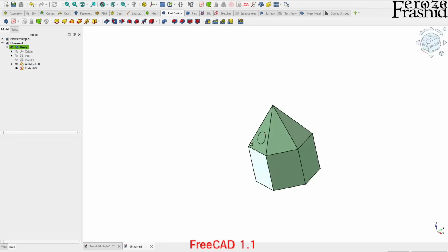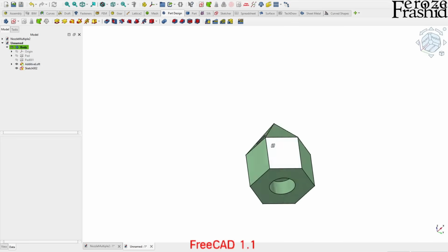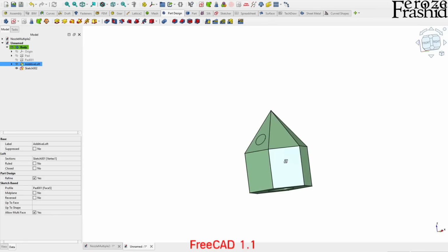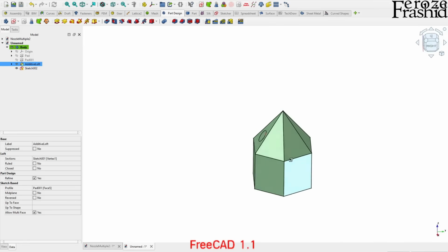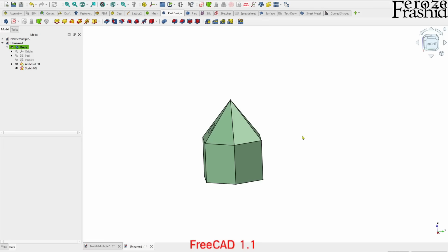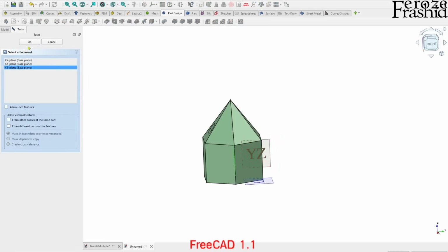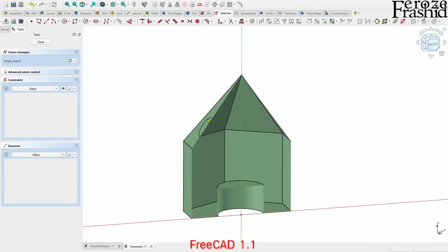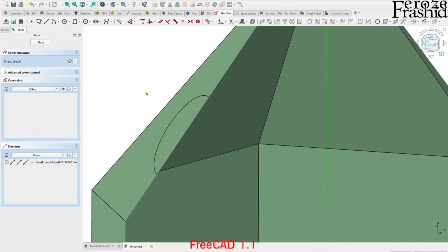Now what I'll have to do is make a pipe with this face and this face. So there will be a smooth transition between them. So we need a sketch to have it. So let's draw another sketch that will be the pipe path, which should be on the YZ direction. So draw a sketch on YZ plane, turn on the section view. I want to pull in this cross section, so I'll just make it a reference line. There it is.